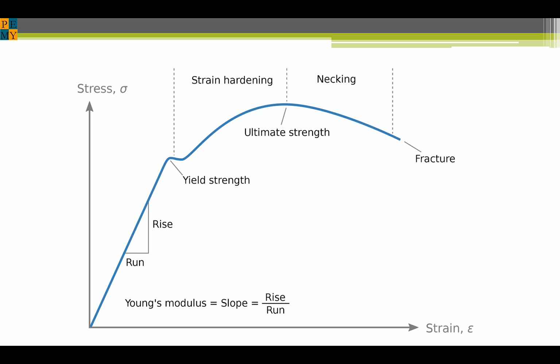The stress-strain curve for real materials varies tremendously. Here is an example for steel. And even within the steel group, the stress-strain curves are all different. But there are some common features that we can cover now. You have the proportional limit, or elastic range, as shown here by the straight line. In the literature, you'll hear an upper and lower yield point, but in practice we simply call this region the yield point.